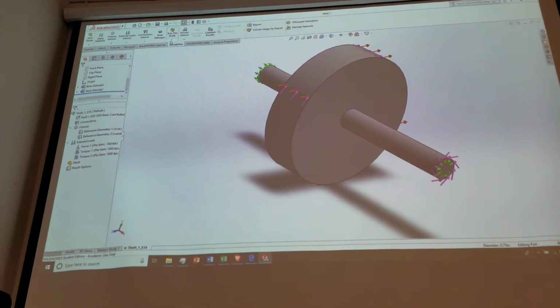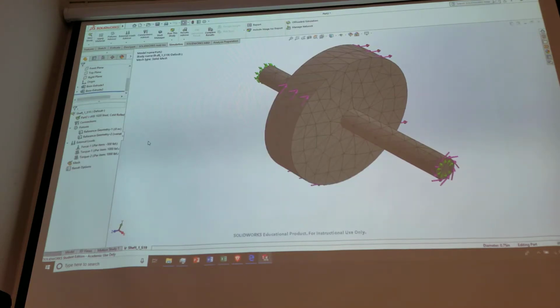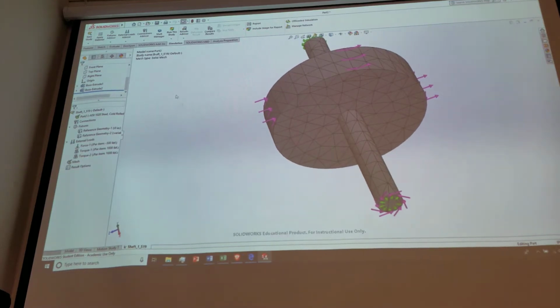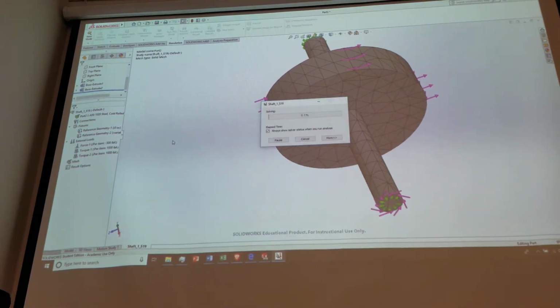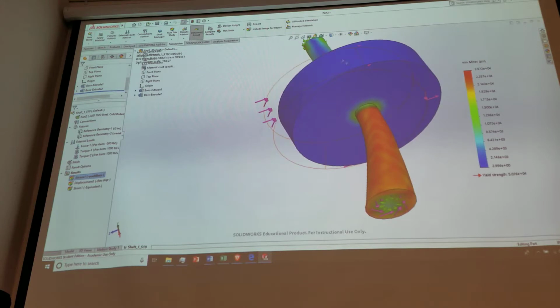And so we can go ahead and mesh this up. Again, I'll run the density down just to see what happens. Right? We got a mesh, not a real good mesh, but we got a mesh. Right? We can run it and see if it likes it. Okay. Okay, well, I got a lot of torque in there, right? So my torque is probably a little bit big. 1,000 inch-pounds on a 3/4 inch shaft is probably a little bit big.